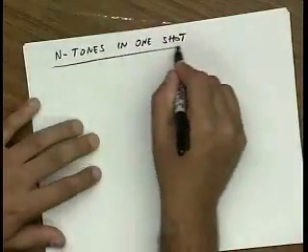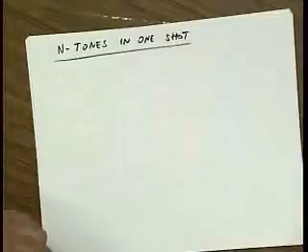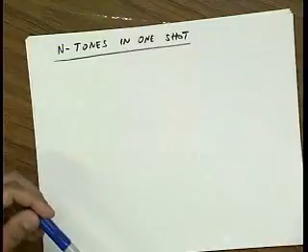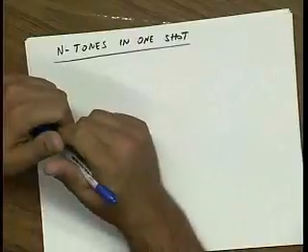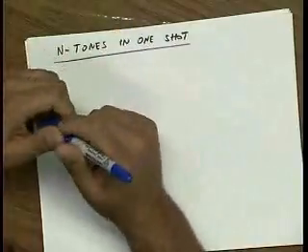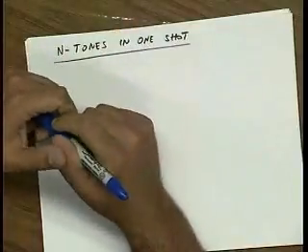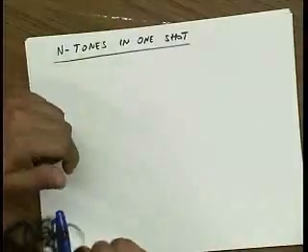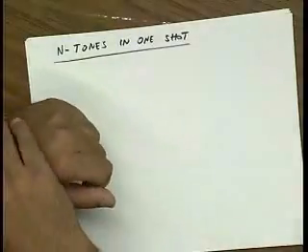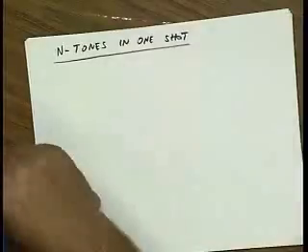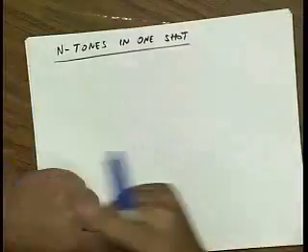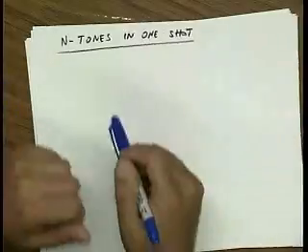In other words, if you look at the way we've solved the distortion problem right now, it's kind of been longhand. We've put in one tone, we've taken powers, we've seen that it generated harmonic distortion. Then we put in two tones, and we saw that you can get intermodulation from the second order and third order. I'd like to give you guys the tools to analyze the problem of having n different tones into an arbitrary nonlinearity, or let's say n tones into an mth order nonlinearity.